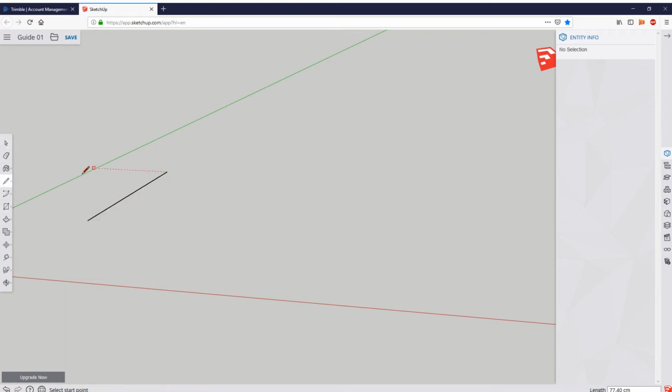Okay, you can do a line, you can keep it parallel to the axis, the line changes color when it's parallel, and I wanted to do a 70 centimeter one. So you see, I can click it and then just type 70 there. And it makes the job a lot easier to keep the lines the size you want. It's a lot more difficult if you actually use, for example, the rectangle tool, because it doesn't allow you to change the lines as easily if they are connected on two sides. So this does make it easier. So I wanted it like that, and I'll say that you want 70 centimeters high.